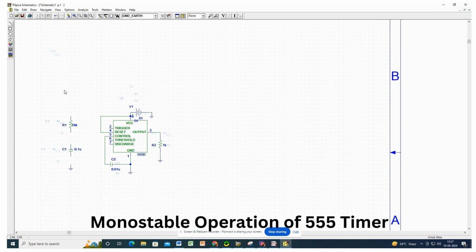So as you know the operation of the monostable, when the trigger pulse is applied, then we'll get the stable state, right? So usually I connect this resistor and capacitor, and this point as usual connected to eighth pin. This point connected to sixth pin, and this seventh pin shorted here. So that's all about the connection. But on the second pin we are going to connect the trigger signal.